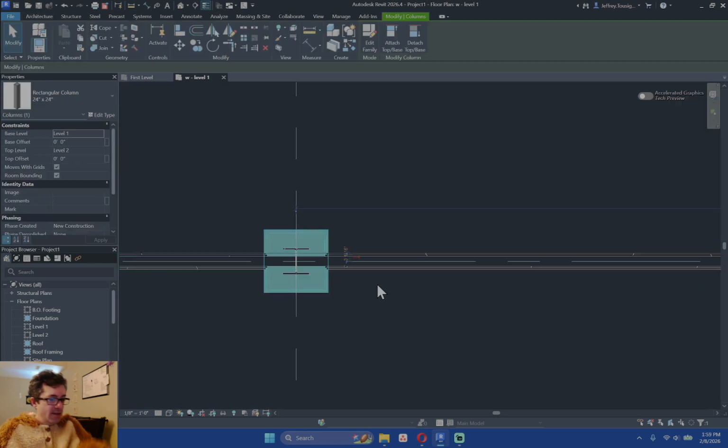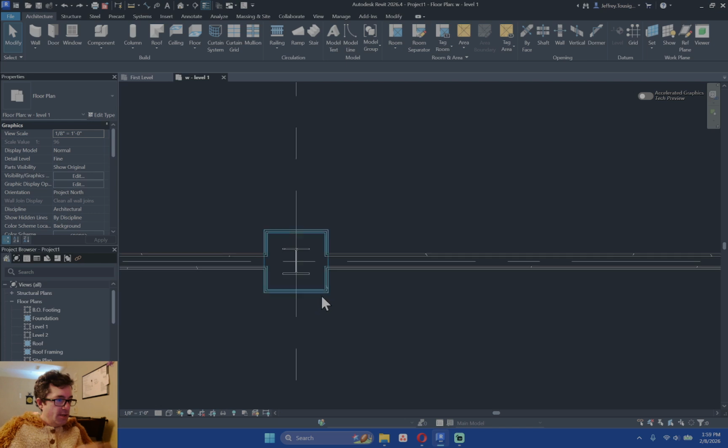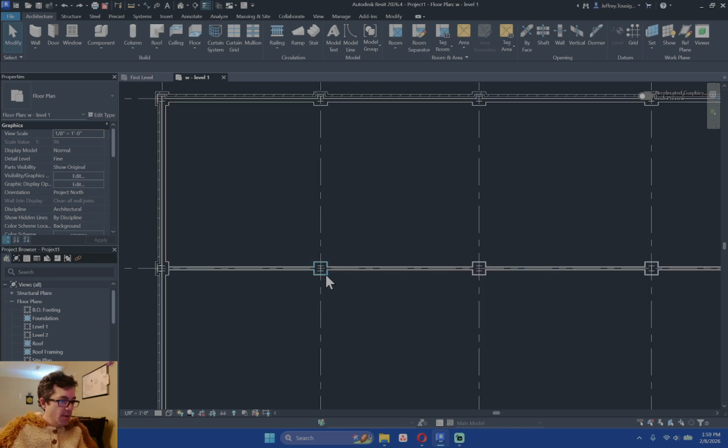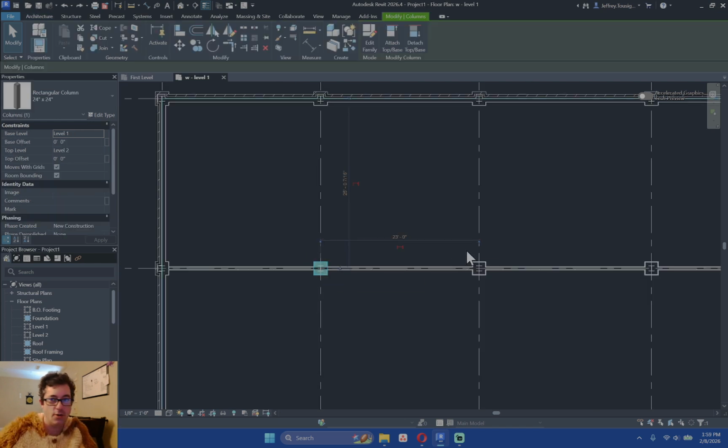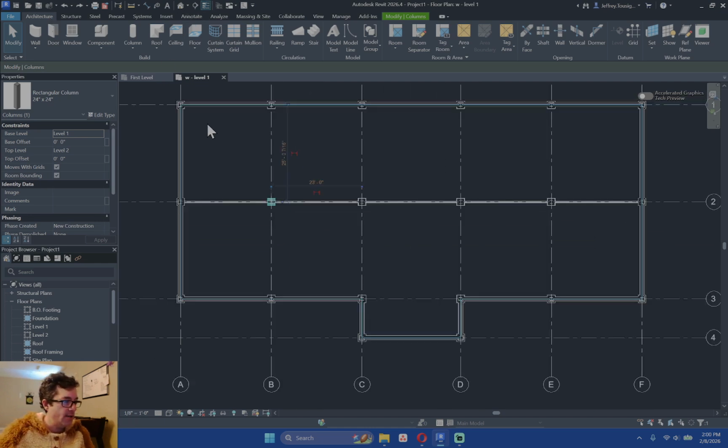If we did not have our architectural columns there, the wall continues through structural columns. So that's one big advantage of the architectural columns. Structural columns export data so that you could do analytics for structure. Architectural columns are really good for merging to actual walls and graphically showing it aesthetically correctly.